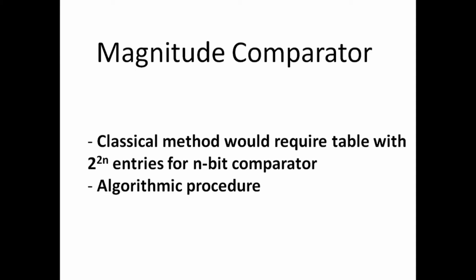Then in total we would need 8 inputs, and that in turn means we would require 8 variable maps, and that would require 2 raised to power 8 entries in the truth table. So in case of 4 bits, we would need 256 entries in the table. That means 256 rows in the truth table and 8 variable K-maps to simplify the corresponding Boolean functions.